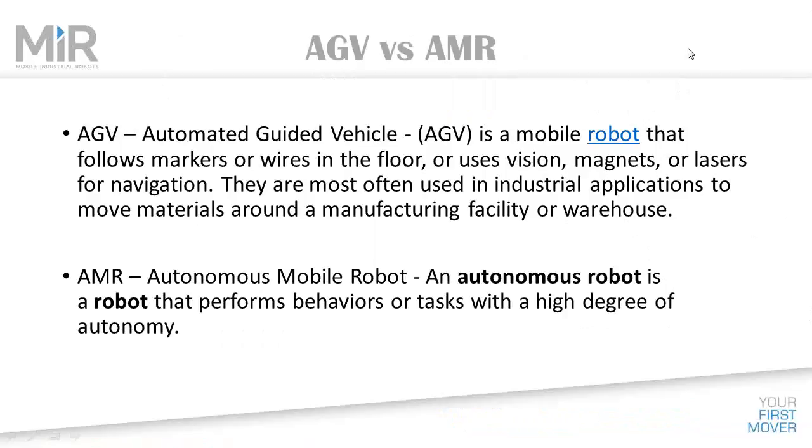So an AGV is a robot that generally follows a predetermined route within a plant, and oftentimes that is guided by either wires or magnetic tape or some remote lasers and some prisms. And so the drawback with those sorts of applications or applied products is that if you need to have the route changed, there is some work that needs to be done to the factory itself. If there's an obstruction that gets in the way of the robot, it is paused there until that obstruction is